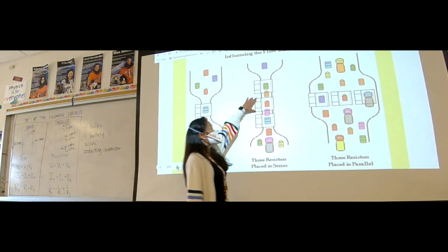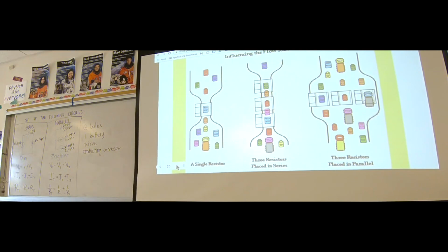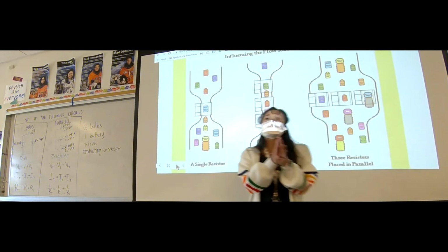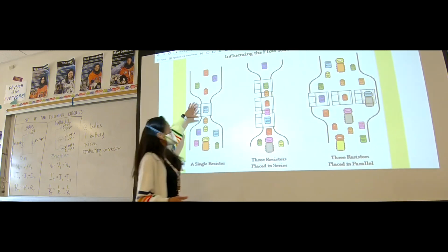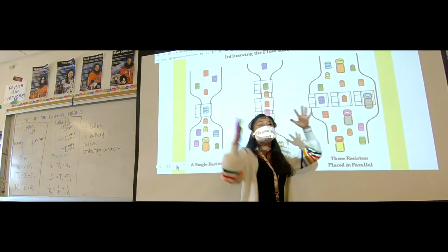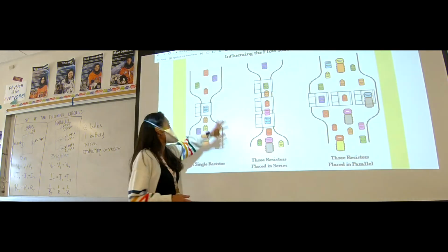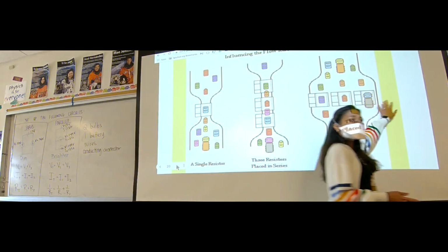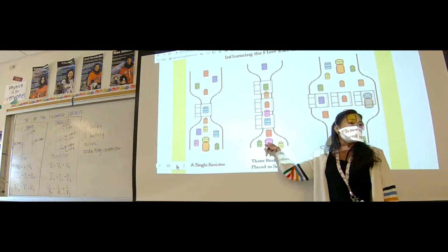But resistors in series, if you had to go through 3 toll booths, one after another, you would hate your life, right? And then the way they actually set toll booths are in parallel, because this is even better than this, which is why I'm saying if you have resistors in parallel, it actually reduces the total resistance as opposed to just having one resistor, because now all these cars have multiple paths to travel through rather than just one. But obviously this is better than this, right?